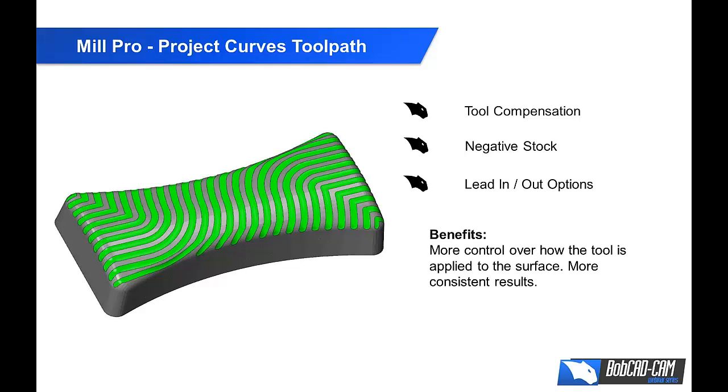Now the benefit of the Mill Pro Project Curves toolpath is you have more control over how the tool is applied to the surface, and you also get more consistent results. So we'll look at some examples there.